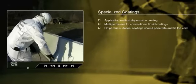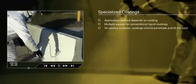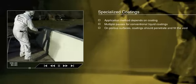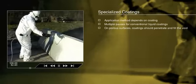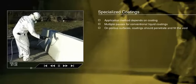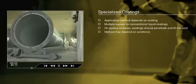Coatings used on porous surfaces should be able to penetrate and fill the surface voids in the substrate, and should be thinned if necessary to ensure penetration. The choice of coating method may depend on the available skill of the workers and the equipment that is available.